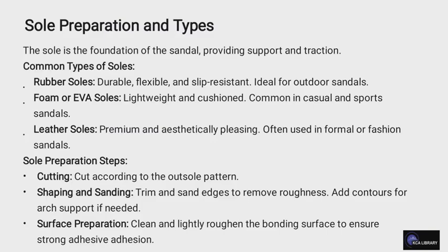Looking at sole preparation and types, the sole is the foundation of the sandal, providing support and traction. Common types of sole include the rubber sole, known for durability, flexibility, and slip resistance, and ideal for outdoor sandals. We also have the foam or EVA sole, known for being lightweight and cushioning, and common in casual and sports sandals. Another is the leather sole, which is premium and aesthetically pleasing, often used in formal or fashion sandals.